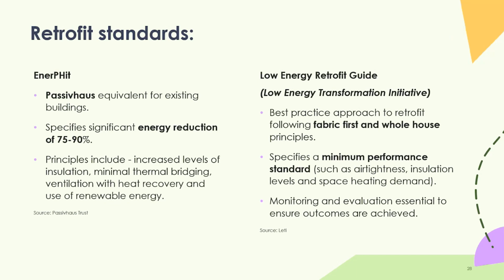So I briefly mentioned some of the retrofit standards earlier. I think I talked a little bit about Retrofit, which is the Passive House equivalent for existing buildings. So this is really high-level quality retrofit. In my head, I think of it as a bit more Grand Designs rather than at scale. But it's all about increasing the levels of insulation, minimal thermal bridging, and a lot of ventilation with added heat recovery systems to make things as efficient as possible.